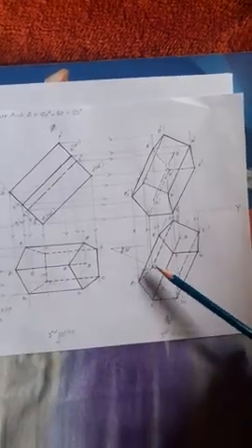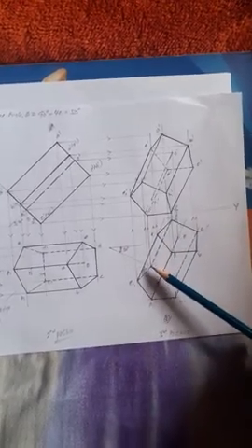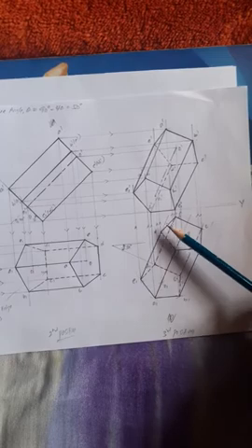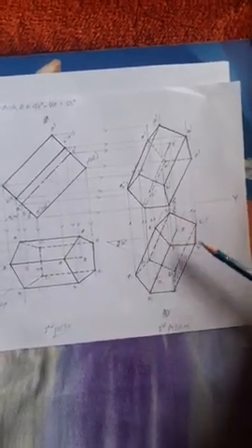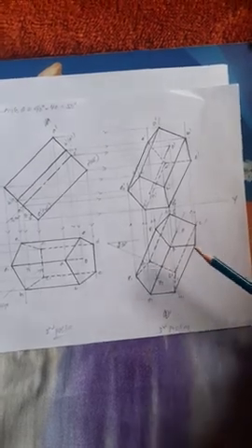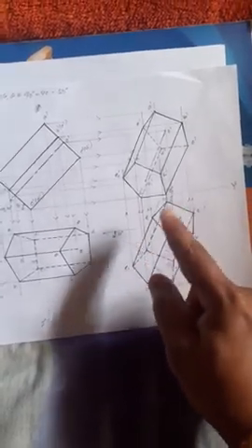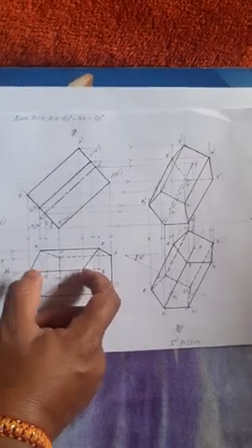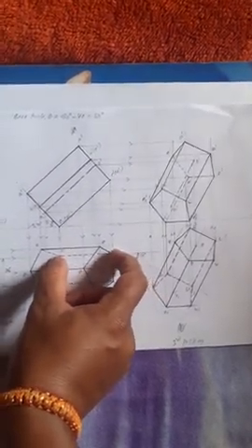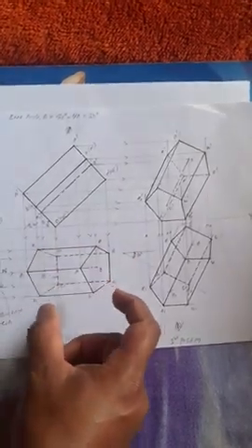Just from D1 draw a 90-degree line to the 30-degree line. Draw a line perpendicular to the 30-degree line from each corner. Those lines are parallel to each other, right? Along that line, just measure any one rectangular face edge. Take D1 D, since all the rectangular face edges have the same length.